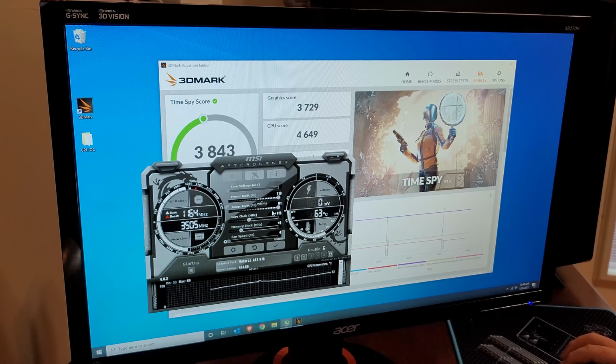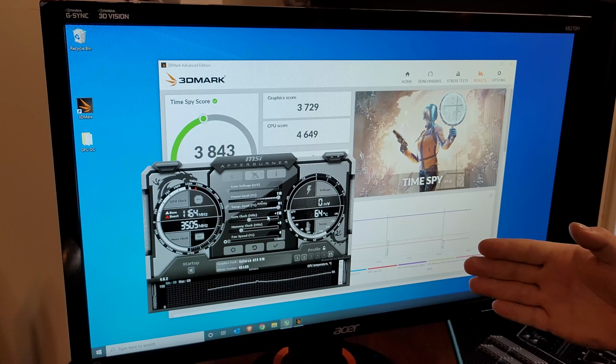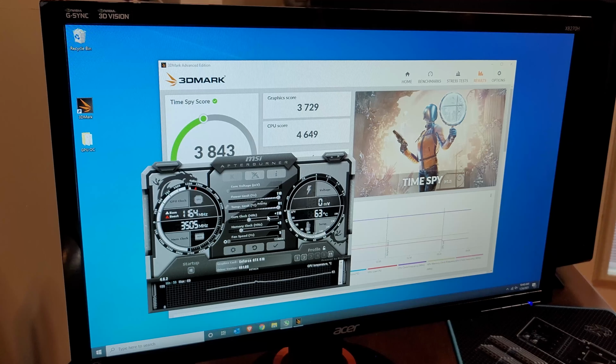And what I would suggest is, getting to this point, you're going to want to move up in small increments. I'm going straight to 110 because I know the graphics card can handle it. However, you may want to start at 50, 55, 60 and go up from there. And every card's different, even if you have the exact same card as mine, because it's silicon lottery. And the GPU itself, you may get really lucky and get one that can overclock really far, or you may get one to where if you just try to overclock it a little bit, every time it shuts down. And it is just a lottery, and you get what you get, don't throw a fit.